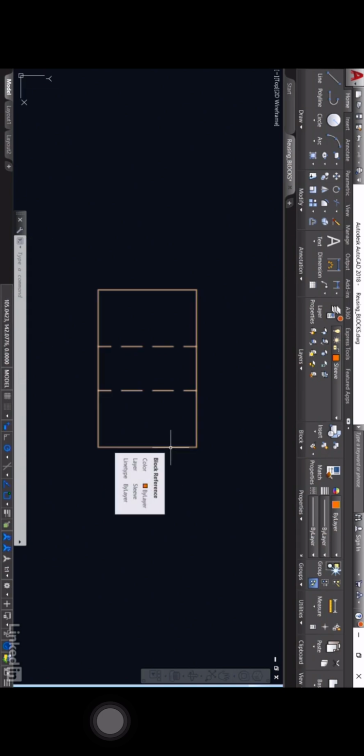So once we've got all of that in place, when I click on OK, what you'll find is that it has changed color, but it's also changed its properties to become a block. As you can see, it's a block reference now on the layer sleeve. Because it was on the layer 0 when it was created, it's adopted the current sleeve layer. Now, if I select that, there's the insertion point as a grip, and I can move that around if I want to using grip editing tools.